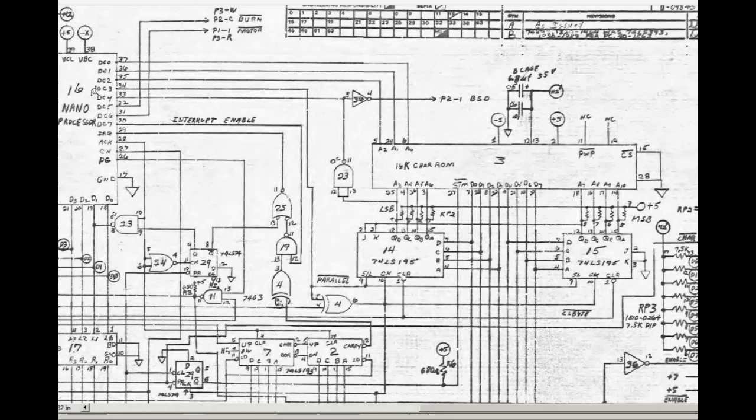It might appear that it's coming out of the processor, but it's not. Just bear in mind these direct output pins on the processor are bidirectional, so if the Nano processor enables one of these pins and tries to set it high, it does that through a current source, and it's quite a low current that is provided to pull that pin high, but it means that an external device can pull the pin low, and the Nano processor can also read that value in.